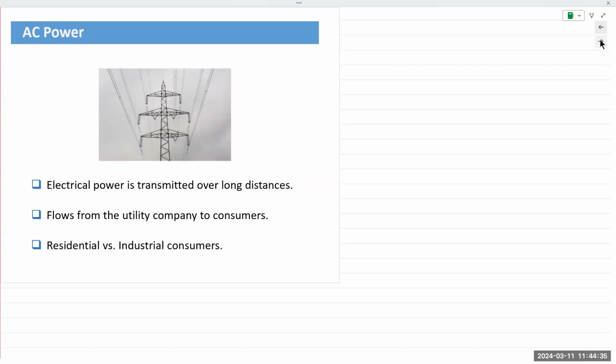You would simply plug it into the wall and say, hey, it works. Let's just use it. Well, the heater would end up drawing too much current from the power outlet. The power strip or the extension cord may not be able to handle all that power. It'll get heated up, and at some point, the wires will just explode, which is an electrical hazard, right? That is the reason why appliance manufacturers stick a warning on there. That is the absolute reason why.